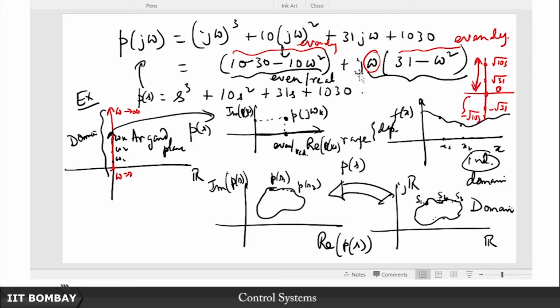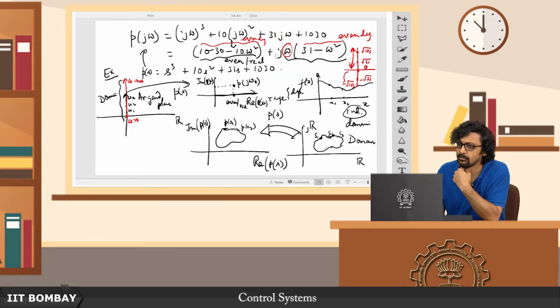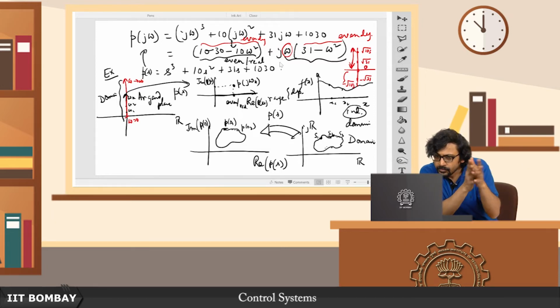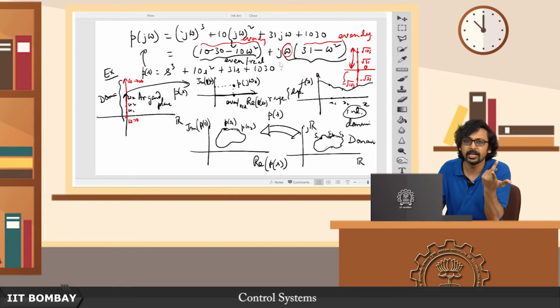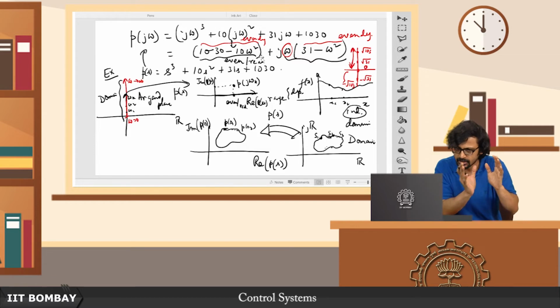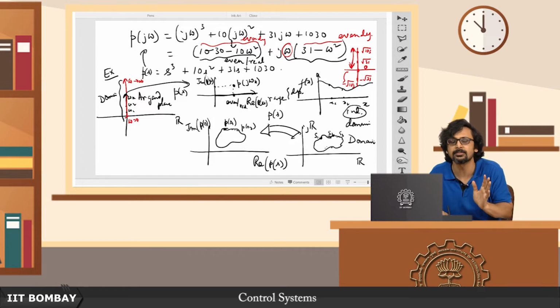We will see that this one indeed turns out to be a polynomial whose roots are not all on the open left half plane, but we have already reduced this based on our observation here. So what Routh will do is formalize this process, and give us some more machinery, some more tools at our disposal. Already with the study that we have done, we can try it out on this particular example here and deduce that this polynomial, even without evaluating its roots,